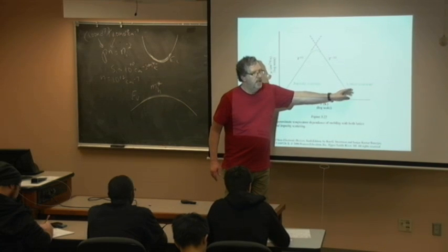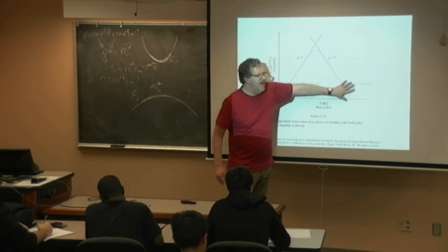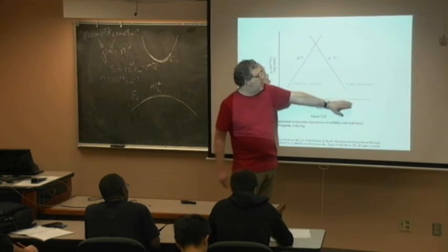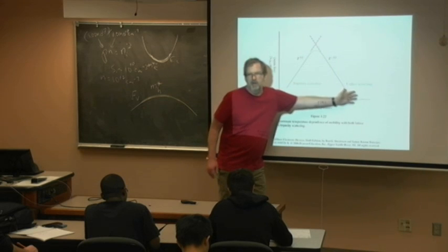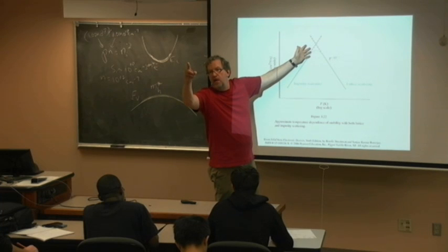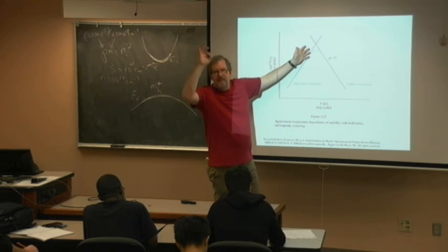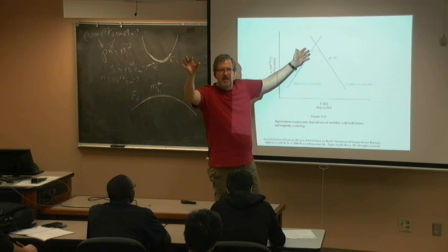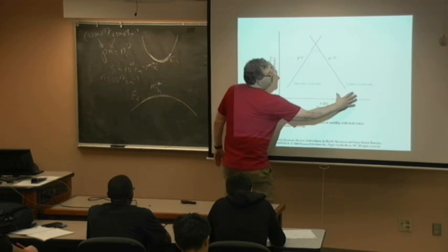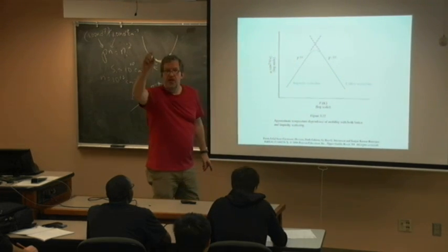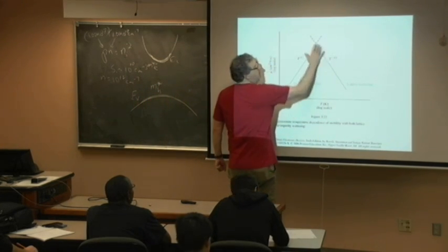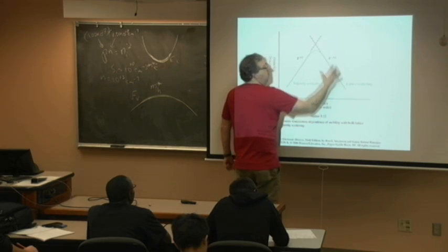Lattice scattering is what? It's not a good name choice, and so don't blame me. Some predecessors chose it. What is lattice scattering? What is this really from? Vibration of the lattice and the electrons running into it. Yes. And what is vibrational energy? Heat. Yeah. So this is temperature. So as I make it cold, the vibrational energy, the phonon population shrinks. I get less scattering. So as it gets colder, it can move better.